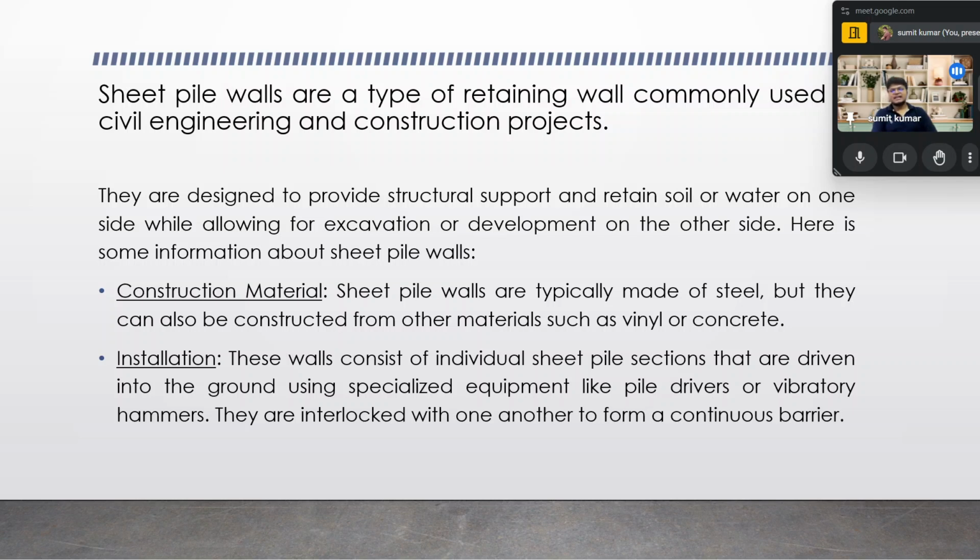When you see, as I take a pin, as you see, if the sheet pile walls are installed in the circular cross section and the water body is over here, all around, it will restrict the flow of water inside, and over here the construction workers, the professionals, can go and work with ease without having disturbance of water from outside. So the construction work proceeds.